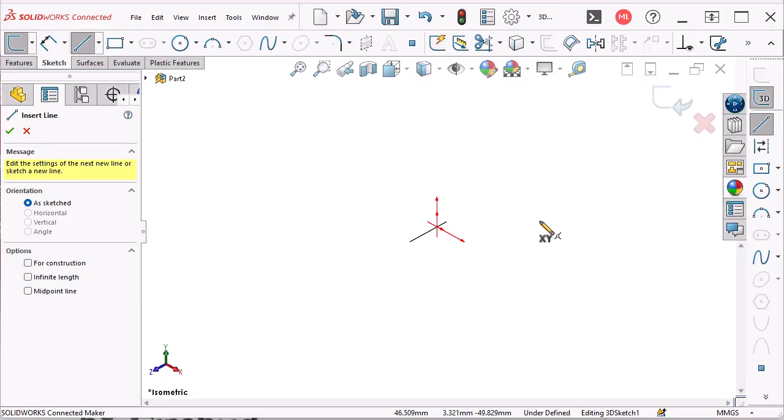Notice that on top of the regular sketch origin, the red sketch origin that's inside there, there's this larger, thinner red sketch origin, which is for 3D sketches. People often start sketching from the origin just to make sure that they have a grasp on reality. And so we'll do that, but realize that even though we're in a 3D sketch right now, anything that we sketch is going to be on the plane established by this red origin.